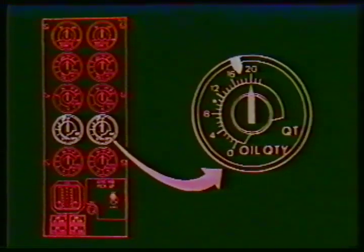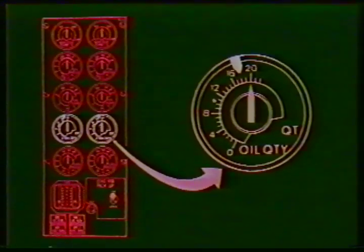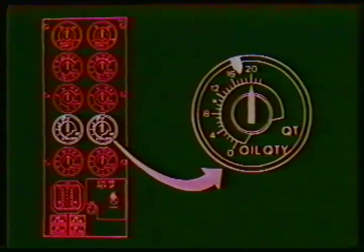Oil quantity indications are sensed at the oil tank. Minimum oil quantity for dispatch is 10 quarts plus 0.5 quarts per hour of planned flight. Maximum oil quantity indication is 18 quarts.